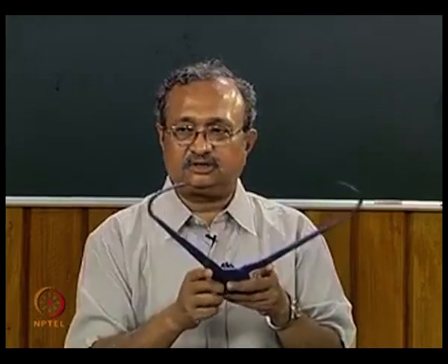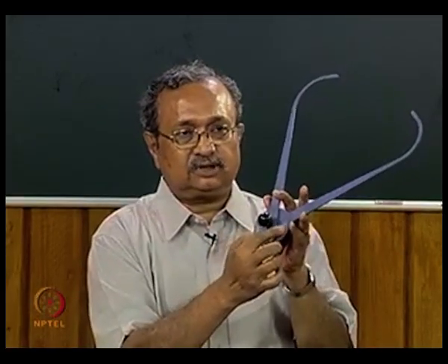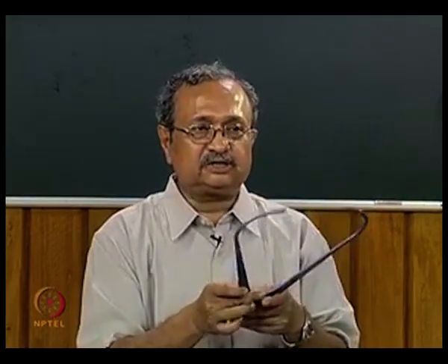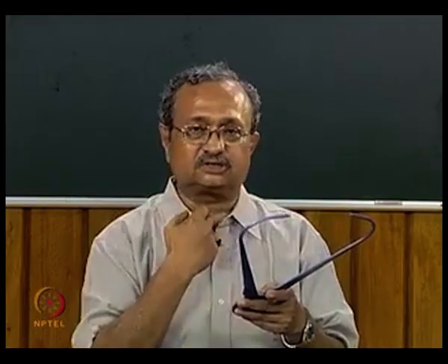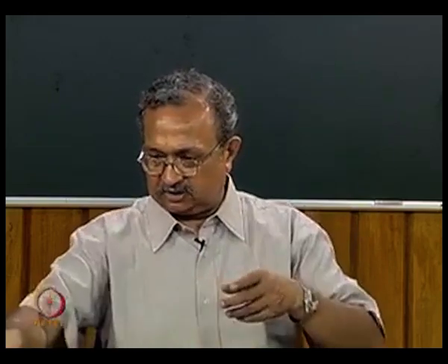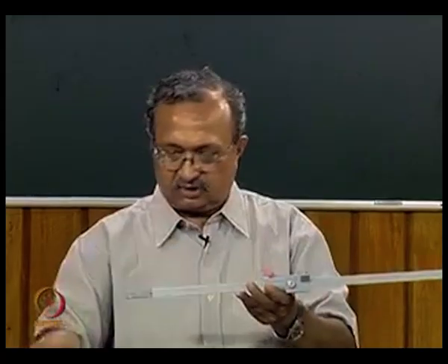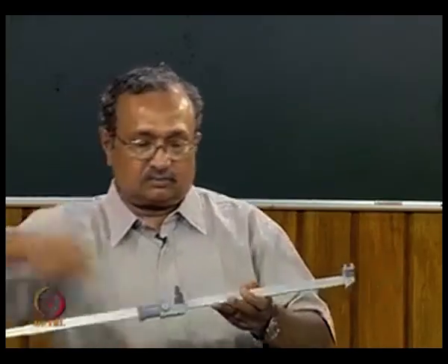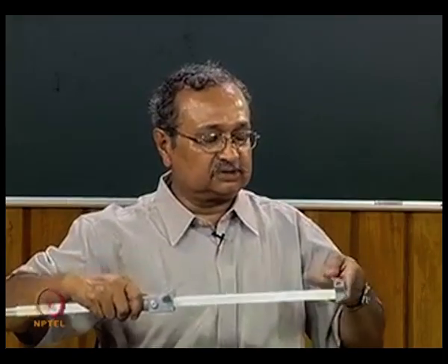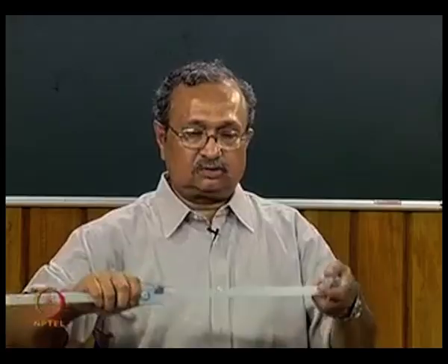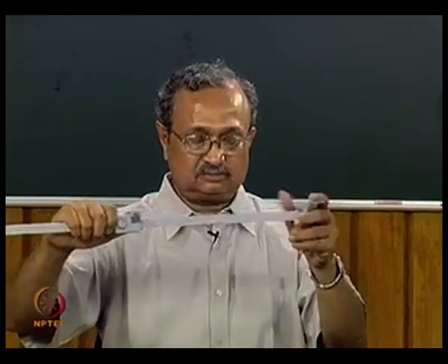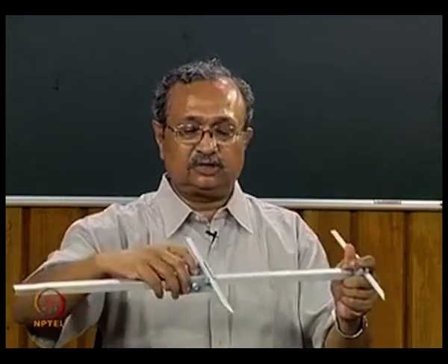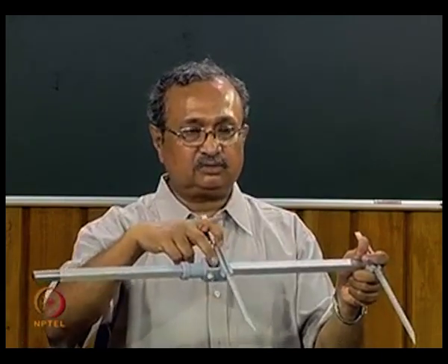Suppose this is required here, in a circular way, the centimeter and millimeter marks are maintained. Normally, keeping one side fixed and sliding the other side like this way with the body in between, we can get the total measurement dimension from here.